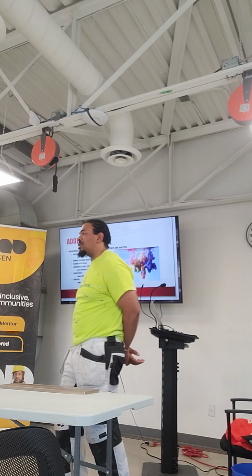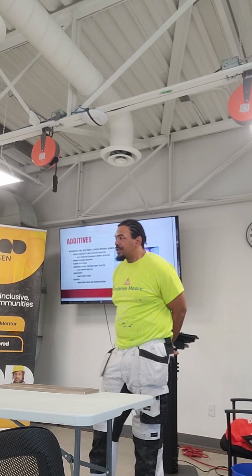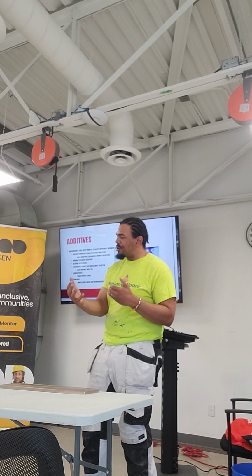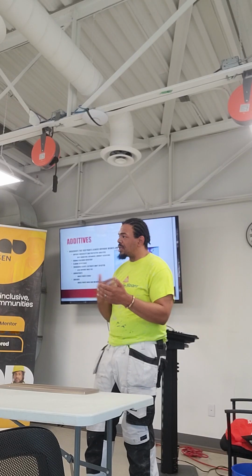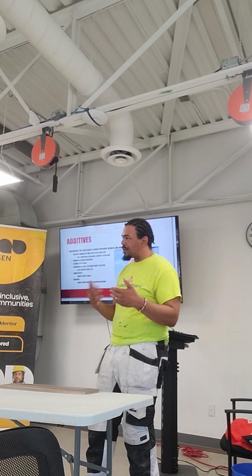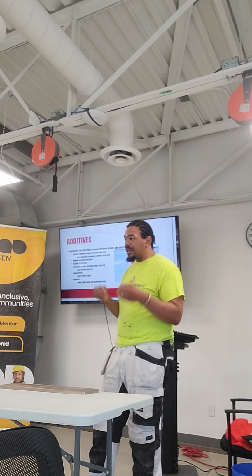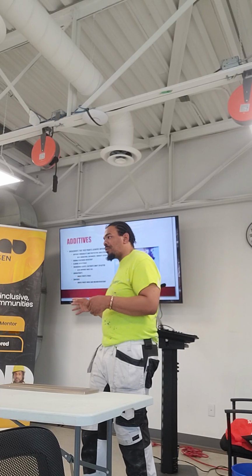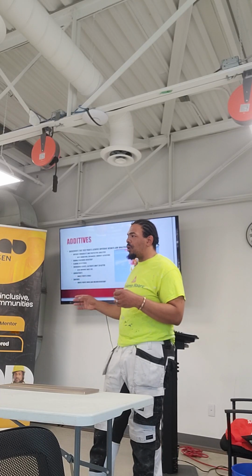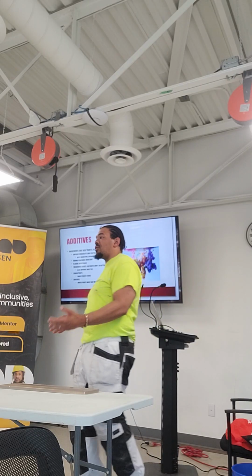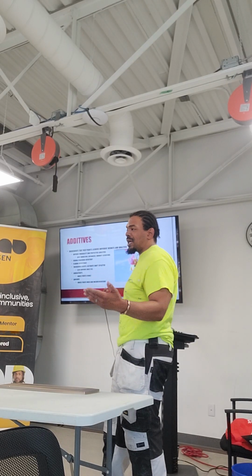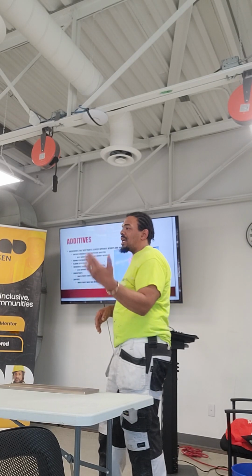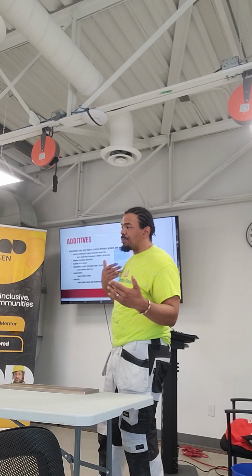I'll give you an example, something called block filler or satin fill. These are designed to seep and absorb into concrete and still let it be breathable, so that the concrete doesn't spoil or break later, so that the concrete becomes ineffective. But it's designed to seep into concrete. Only concrete. It's not really designed for drywall. It won't have the same protective properties. It won't serve the same purpose. And as a matter of fact, on drywall, it's not as effective. It doesn't do exactly what it's supposed to do. So drywall needs to be sealed, where a satin fill will allow concrete to breathe a little bit.